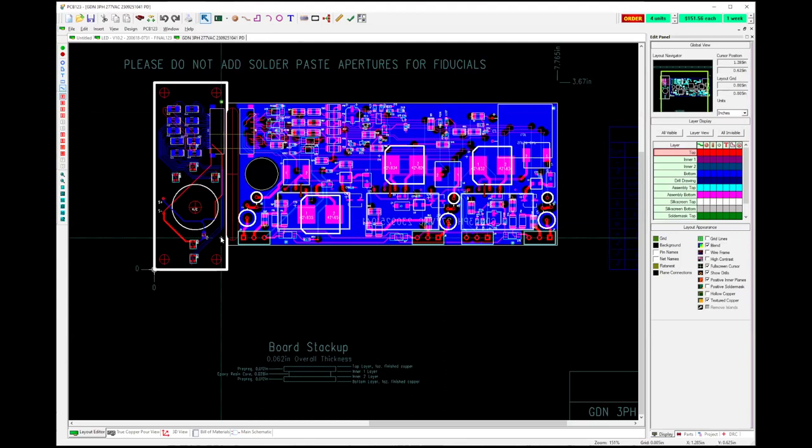So basically it goes like this. You set up your board outline to fit in whatever enclosure you're going to go with. You select your parts, do your schematic, then you go into here, you place the parts, you place them logically so you can route, then you'll have the guide wires. And then you want to route your wires.